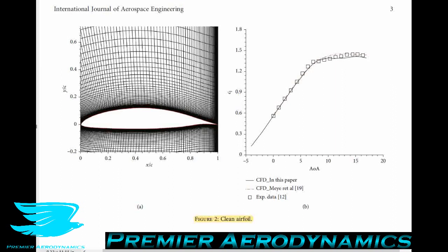So if we don't know what the density change is, so if it's like 1.2 kilograms instead of 1.21 or whatever, then when we do our CFD, we can't take into account those errors or those changes, and we get errors in the CFD. It's not going to line up. So whether the CFD matched the experimental data in terms of the drag coefficient or not, we don't know, but there is a good chance that it didn't because the density of air was not taken into account, I'm pretty sure. So it might have been a couple % error there overall.